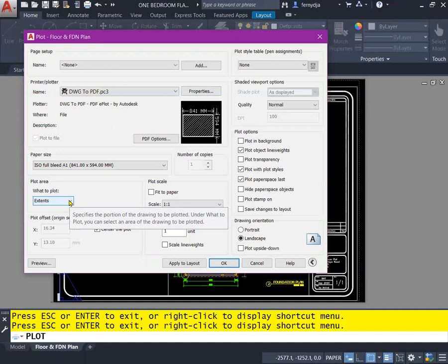If parts of things are off the sheet, it's going to accommodate those on the sheet, and it's going to center that, and it might show the center off. So you have to make sure that none of your viewports come off the sheet if you're going to do that. Keep them within the sheet.